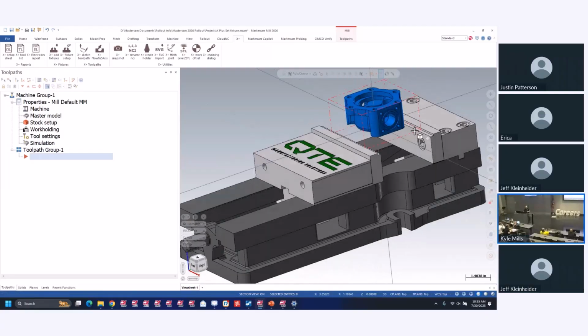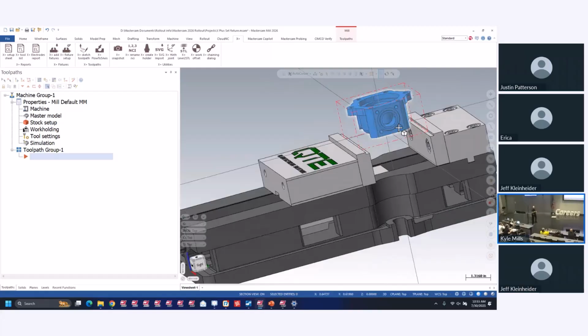And you can see for this one, I set it up to where it's going to go on that little cutout. You have control of where it automatically comes in. And not only that, you can actually set it up to where it goes on the floor, and you can put in the parallel size if you want to use parallels. So for this one, I put it on the cutout because it's just a little cutout there and I want it to be on the top. Well, let's use a different configuration where we can add in those parallel sizes. So I'll just hit undo one more time.